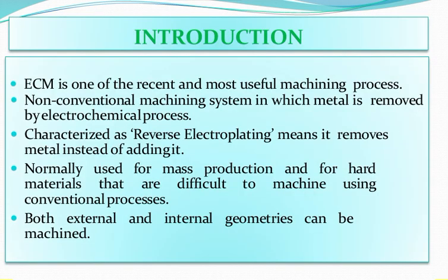Now we are coming to the introduction of electrochemical machining. Basically, electrochemical machining is one of the most potential unconventional machining processes. Though it is a new process for metal working, the basic principle has been well known for a long time. This process may be considered as the reverse of electroplating with some modification. Further, it is based on the principle of electrolysis.